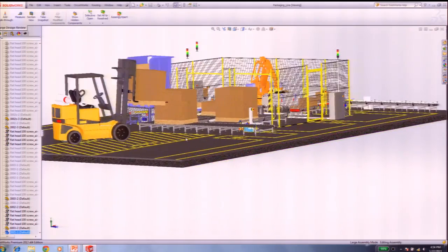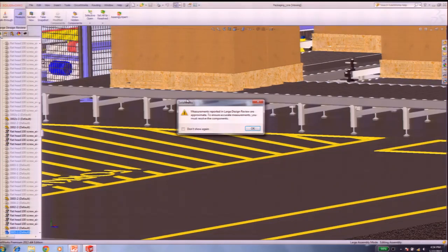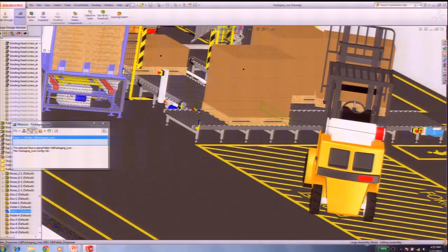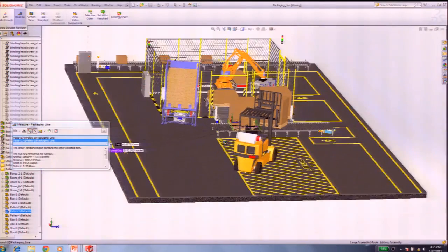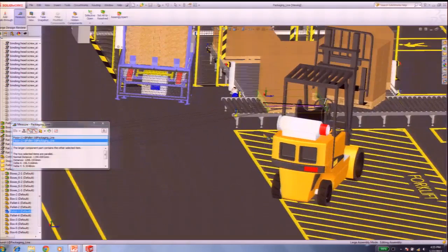Okay. Now, I've got a forklift truck. I've got some pallets here. If I'm interested in a particular measurement, the size of my pallets, I can simply go in here, and as I mentioned, I'm advised that measurements are not to high levels of precision here. If you have a reamed hole, for example, for a dowel pin, you can't measure that in this mode. But if we want to know how big our skids are, whether these are metric skids or English imperial type measurement skids, we can measure something like that easily, or clearances. So I'm going to just turn this off, and you can too. Now I can grab the end of my design here and then go to my other side and find out, using standard methods, how big this item is. A little over a meter, 1.2 meters. So it's a little bit bigger than the 1 meter size I expected.